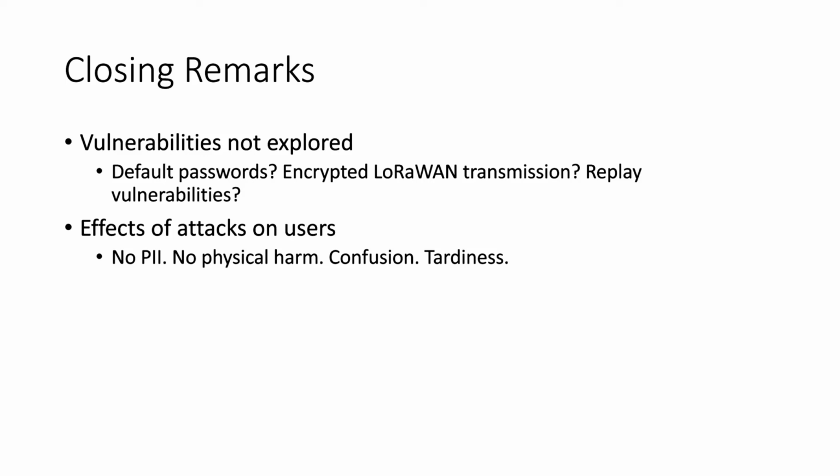And also recall that I didn't implement any frame counting here. And so the system may be vulnerable to replay attacks, where you just capture one packet and save it. You don't need to know anything about its contents. You just need to know that you've captured this packet and it is a valid packet because it was sent by the sensor to the gateway.